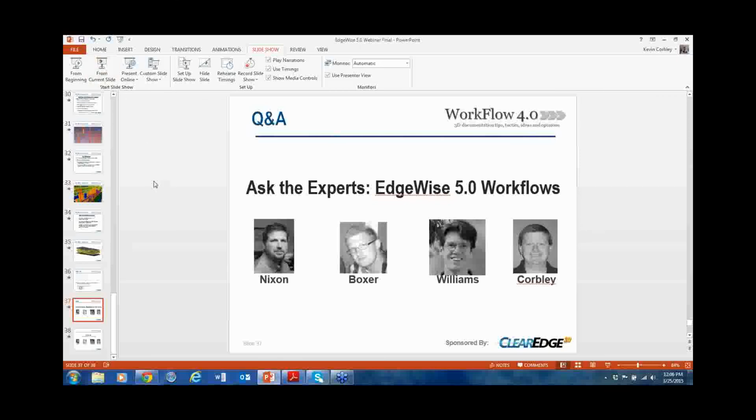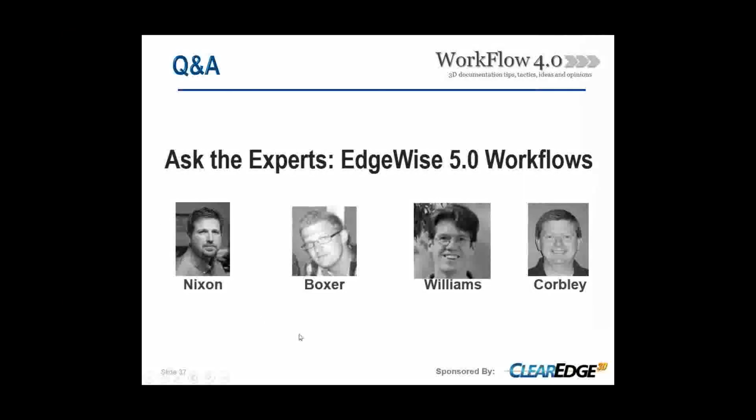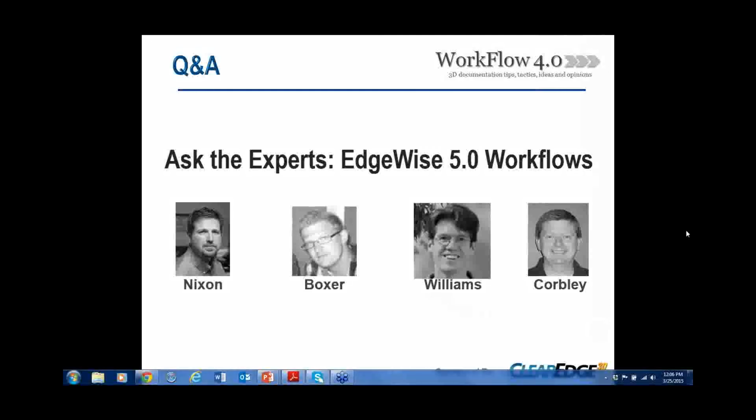Yeah, thank you. So the software is really only going to be as accurate as the point cloud is, first of all. We have a handful of customers whose scans are registered to within 1/8 inch, but most people are fooling themselves if they think they can get that type of accuracy.